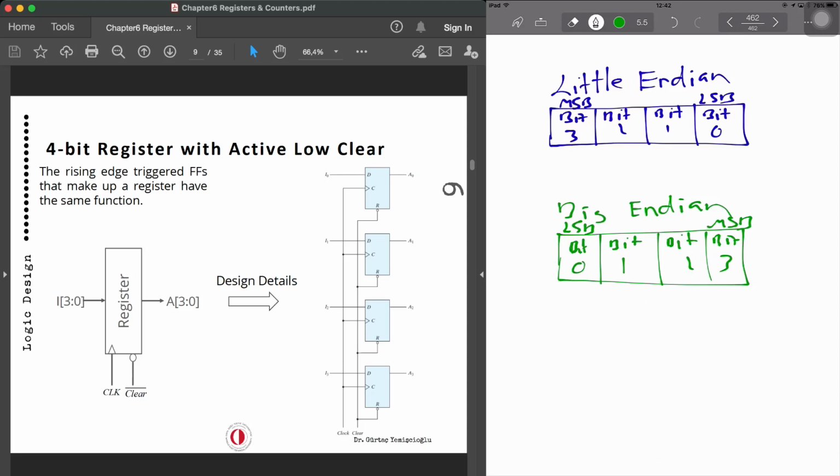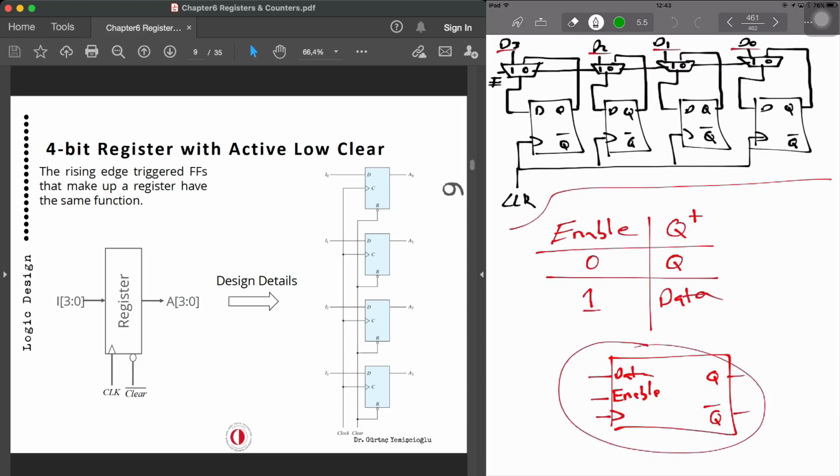It's not working with the clock, and it can easily be demonstrated by adding a reset or clear input. Now, 4-bit register with parallel load, as I already demonstrated over here, it's just a simple multiplexer. So either we select a new one or we hold the previous value.